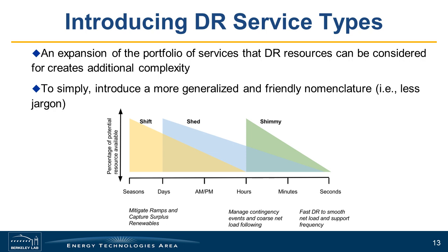They're based on end uses that can take discretionary load consumption from one hour and move it into a different hour. These have pretty significant value for reducing overgeneration during hours of high renewable generation and avoiding some of the multi-hour ramping needs that you would see during the morning and afternoon hours.